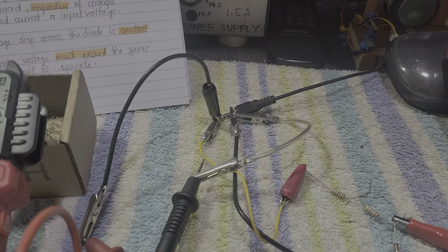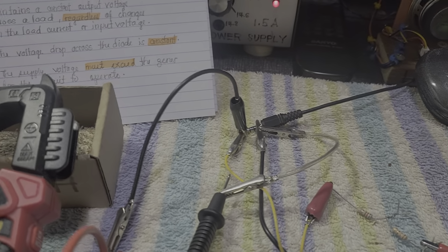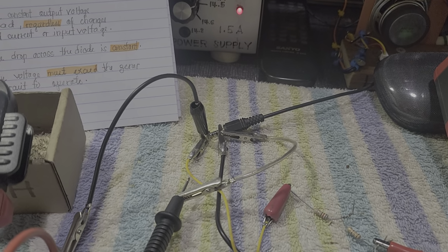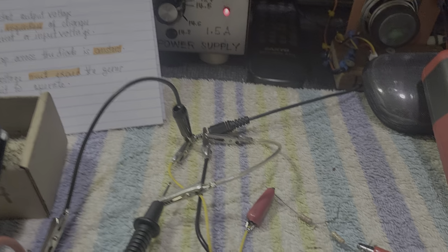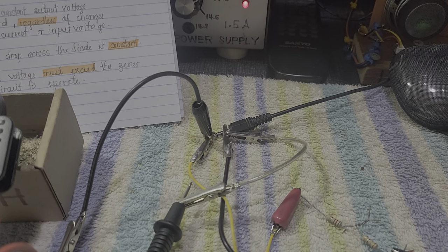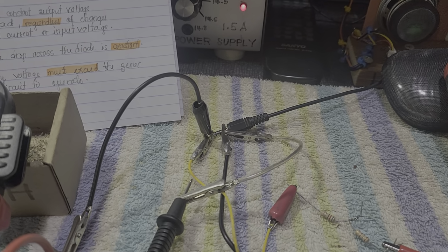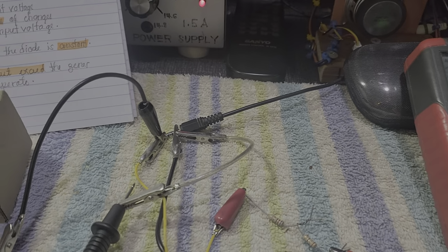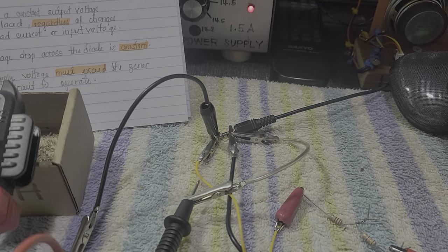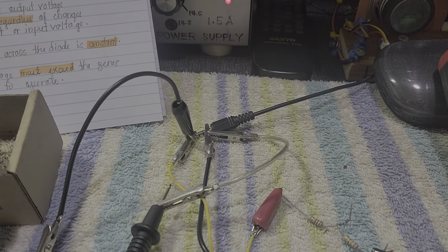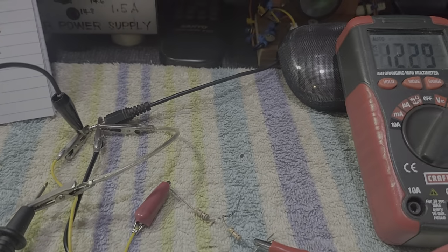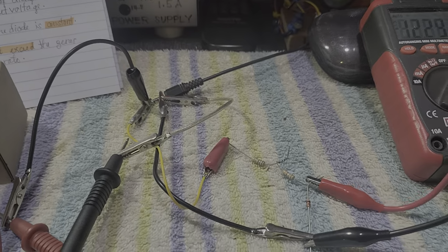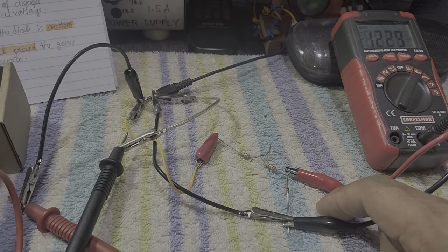I would like to repeat it. A Zener diode could act as a voltage regulator only for those discrete components that do not require high current. The current output of this one may be in the so-called milliampere range. So this is good for a 12-pin IC maybe. For us to stabilize the voltage input to that IC, we could use a Zener diode.